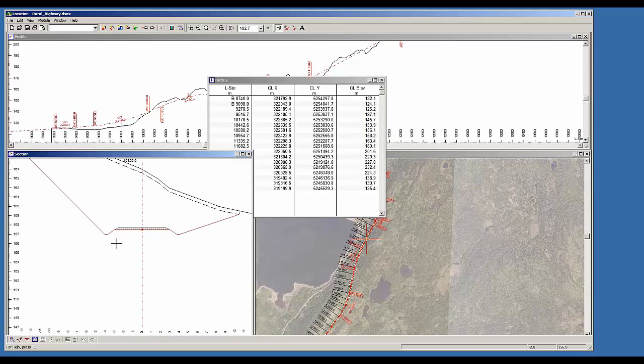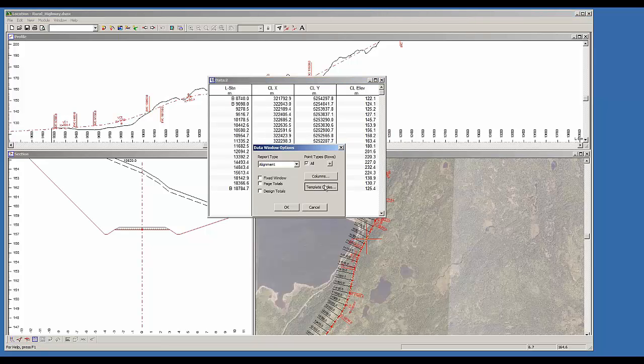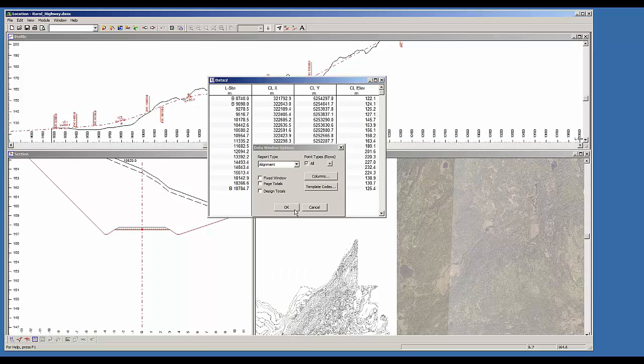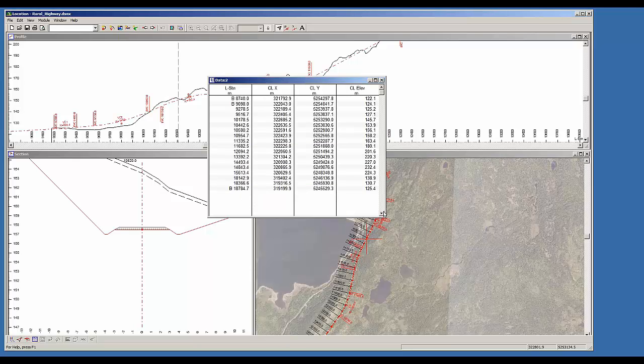So let's suppose I want to export the shoulder points as well as the center line. So I just go into my data options, template codes. I'm going to add REL, and RER. And you see the other ones there, DOL, DI. Once you get used to them, you don't need to do this hovering. You can just set them up, recalculate everything.